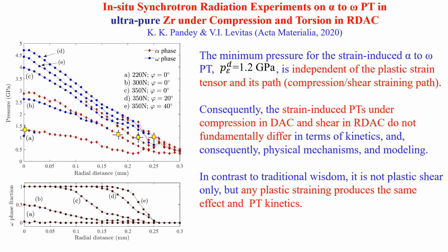So if we reach steady state of microstructure, then we will see similar strong effect. Of course, rotational diamond anvil cell has advantages that it controls independently pressure and plastic strain, and it also allows producing much larger plastic strain, and not only start but complete phase transformation under low pressure.